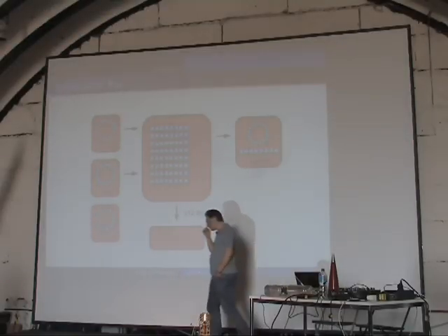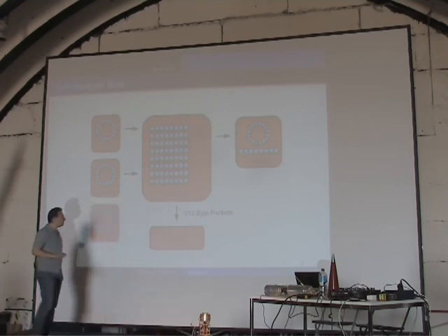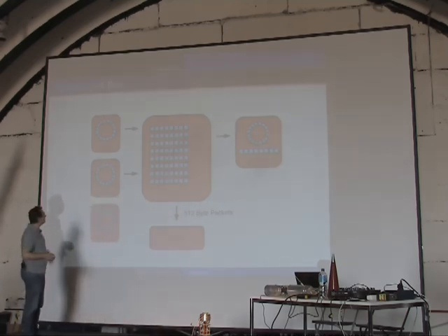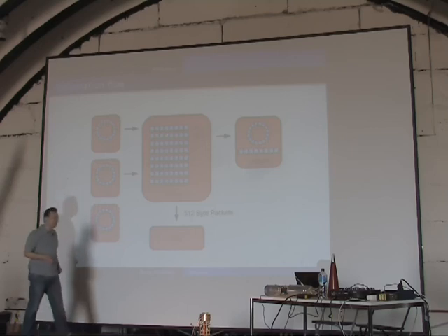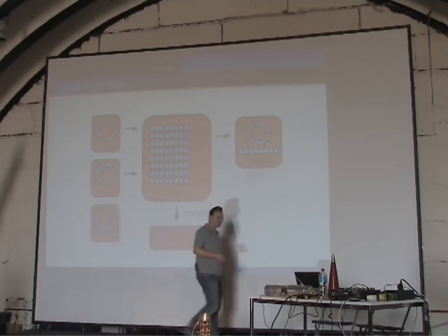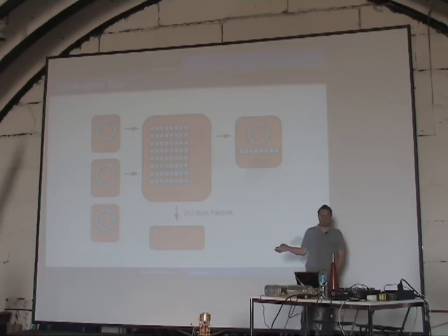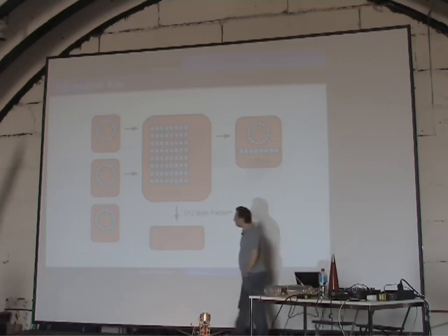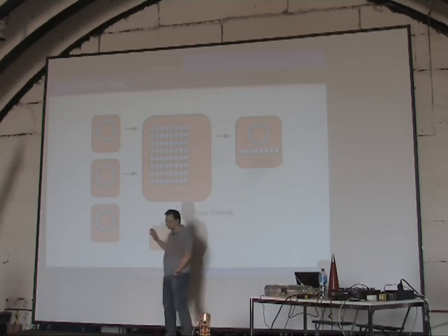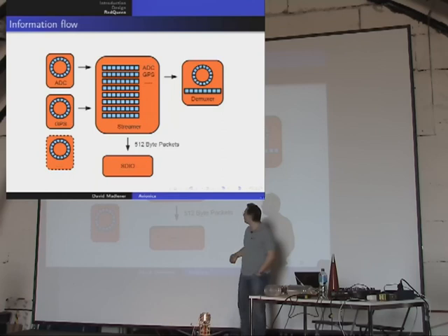at the moment. Everything is made of objects in the Propeller. So every cog is one object. So normally you have sensors producing a stream of information. It may be, in this case, the ADC that is measuring some voltages, or the GPS, or any other sensor you can think of. And what you have to do is you make a ring buffer, and in this ring buffer you put your stream of data, okay?